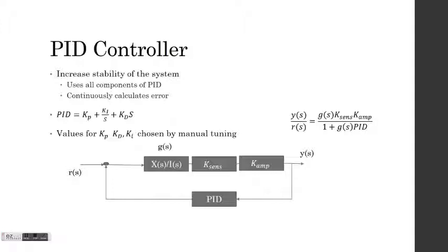I would first set the values of Ki and Kd to 0. I would increase Kp until the output of the loop oscillates, then Kp was set to approximately half of that value. Then I would increase Ki until the offset was corrected in sufficient time for the process. However, if I increased Ki too much, this would cause instability. Finally, I added Kd, which may or may not have been needed depending on the response that I was looking for. I had to be careful not to add too much Kd because this would cause excessive overshoot.